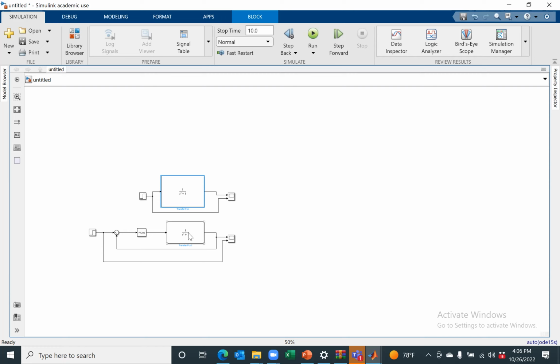Now, what is the problem with proportional control? Proportional control is proportional to the distance or the state, but it is not accounting for the inertia. What that means is even though you have a controller, because of the inertia effect, there is a possibility that this may overshoot. You see your friend on Mill Avenue, you start running fast, but then you pass the friend. You don't stop where your friend is. You actually go past where your friend has stopped. That is the problem with proportional control.